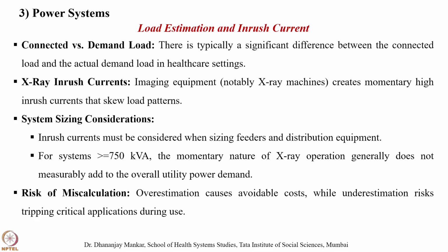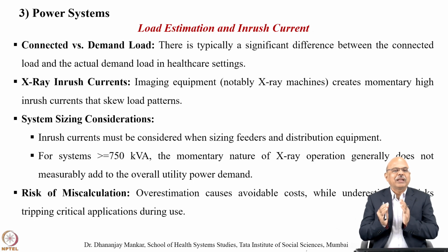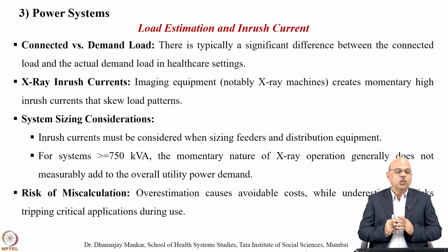Now, for the power systems, what are the load estimation and inrush current? When you talk about connected versus demand load, there is typically a significant difference between the connected load and the actual demand load in the healthcare system. X-ray inrush currents: imaging equipment, notably X-ray machines, creates momentary high inrush currents that skew load patterns. For system sizing, inrush currents must be considered when sizing feeders and distribution equipment.